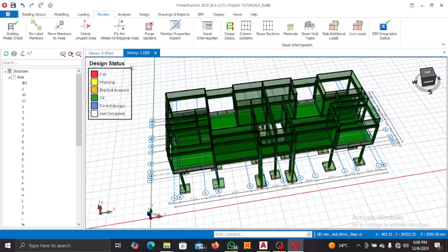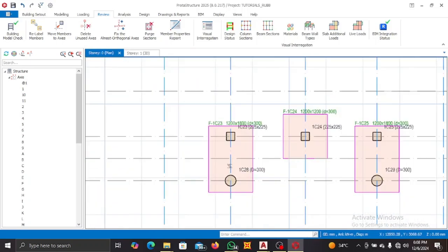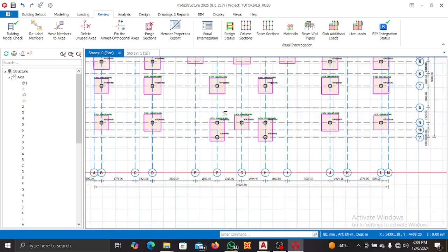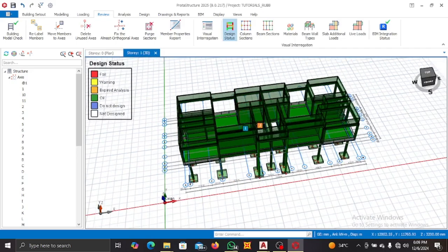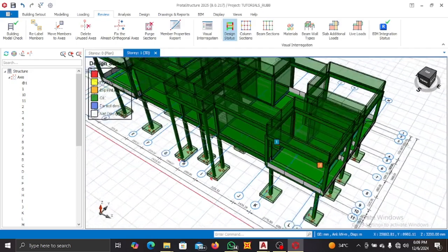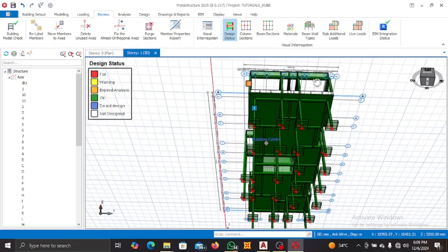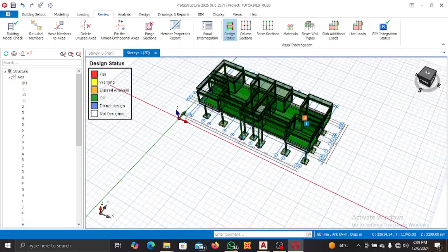All right, and please, just to stress, remember what we did, a combined footing. It's not advisable for your pad bases to interlock, to overlap themselves. So if it overlaps, you just delete it and create a combined pad footing, please. Okay, so that is it for design.